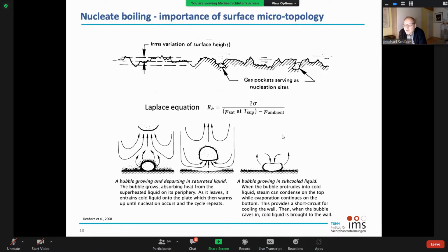And now let's see, there is one comment in the chat: with increase in temperature at the bottom, the density reduces, whereas the temperature at the top is lower, thus the liquid is higher density. Bulk convection, yeah, that's true. We will get bulk convection, but bulk convection we will get anyway. As soon as we have temperature gradients, we get some bulk convection in the system.